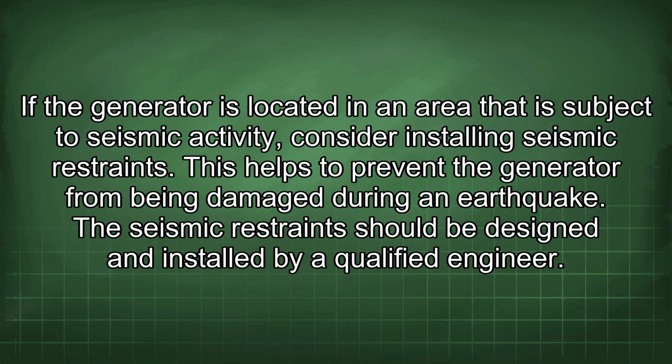If the generator is located in an area that is subject to seismic activity, consider installing seismic restraints. This helps to prevent the generator from being damaged during an earthquake. The seismic restraint should be designed and installed by a qualified engineer.